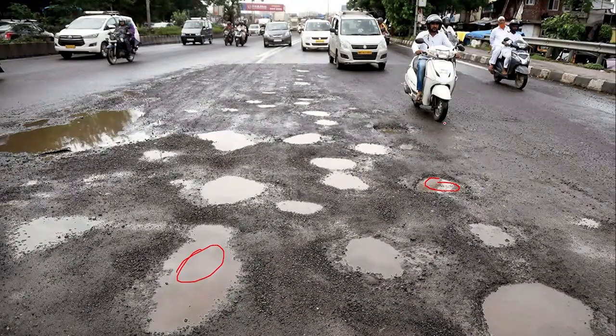For example, if you are riding a bike on this pavement when the water stands on it, the skid resistance and the friction generated between the tires and the pavement will get reduced. If you apply the brakes, there will be a chance of your vehicle losing balance, and you may fall, and an accident can take place if there is not sufficient skid resistance.